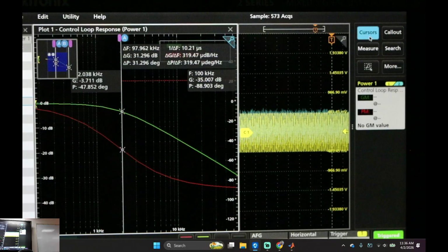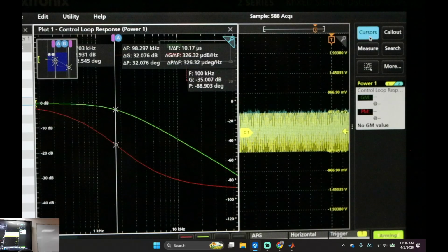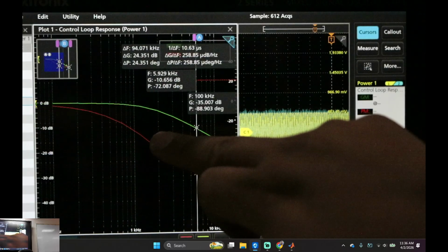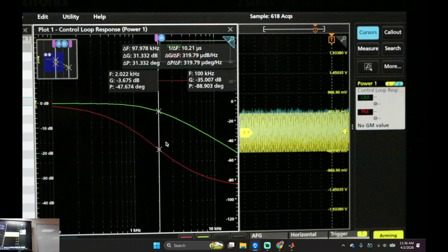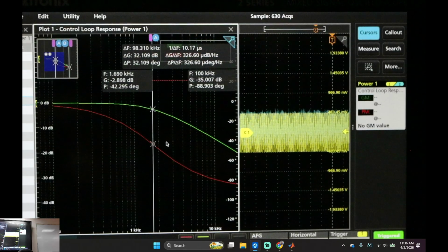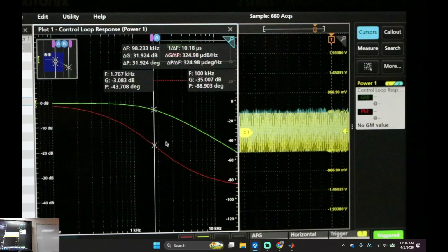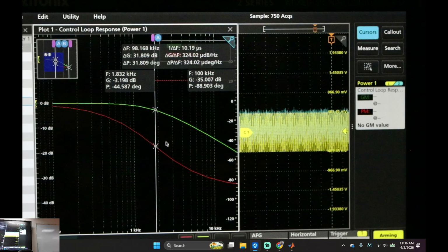And where is our 3 dB? How do I get rid of this screen? It's right there. Okay. Fine. 3 dB. There we go. What's the answer? 1.783 at 3 dB down, minus 3 dB. What's the phase? Actually, I think the phase is better. If I go to minus 45 degrees, that's an easy number to memorize. Right there. Is that the answer?